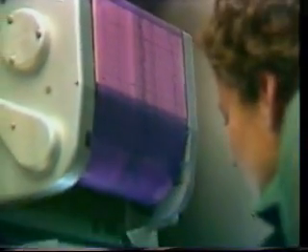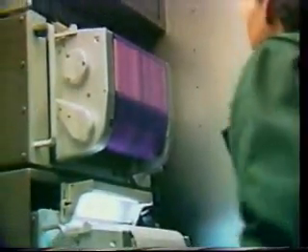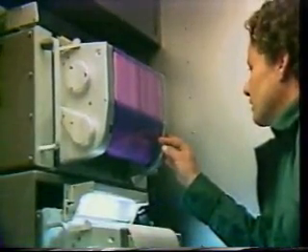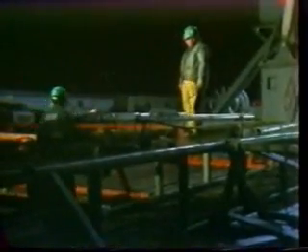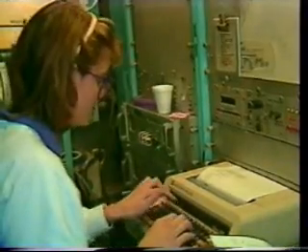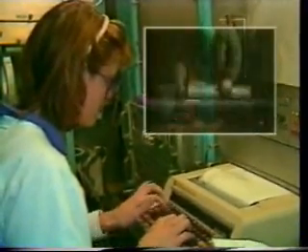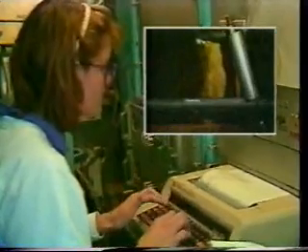The logging engineer must check to determine that the logging tools functioned normally and responded accurately to downhole conditions throughout the run. A quality control scan of the logs is usually done to verify this. Additionally, the logging crew must complete the after-survey calibration check. This involves repeating many of the same calibration checks that were carried out before the logging tools entered the hole, and entering these after-survey results in the tool check summary of the final printout of the logging survey. Such after-logging calibration checks are needed to confirm that tools responded consistently throughout the run.